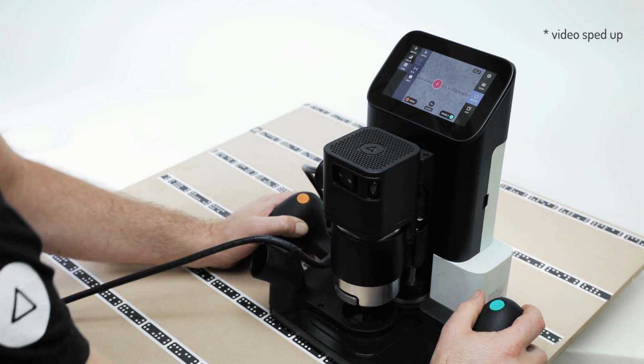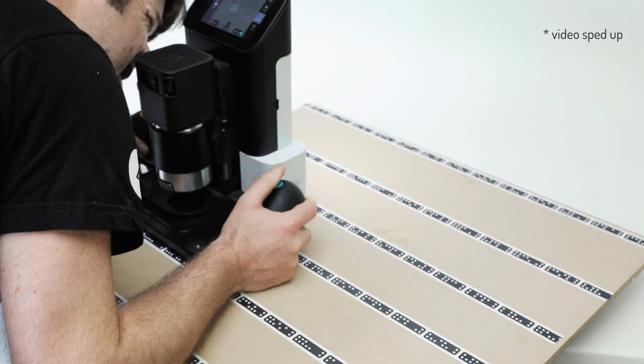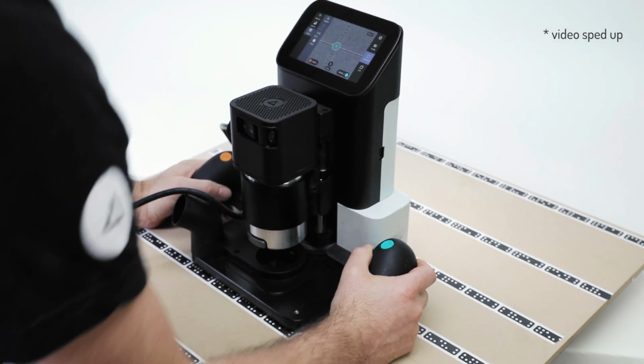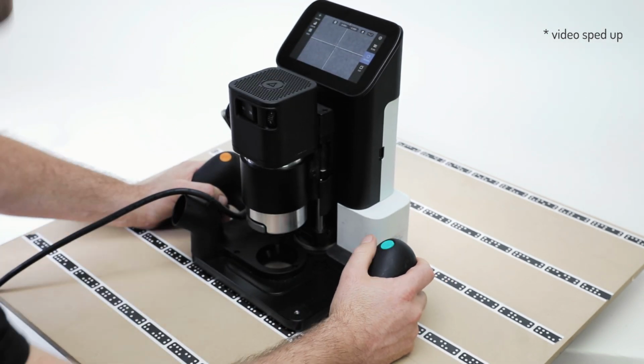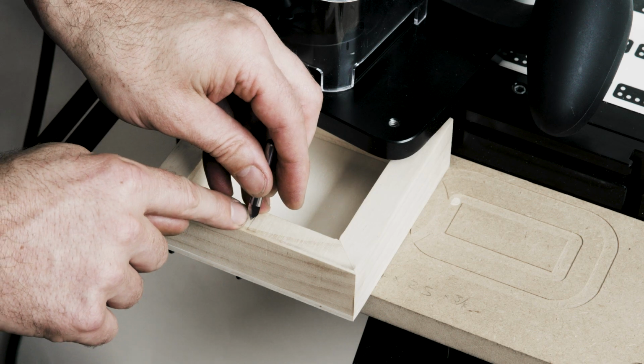There's also the entirely visual approach. If you had a chalk mark in the middle of a floor, you would probe 3 times with the point of an engraving cutter hovering just above the surface. You'd do the same thing using the center of the cutter as your reference point, looking at this, not the screen.